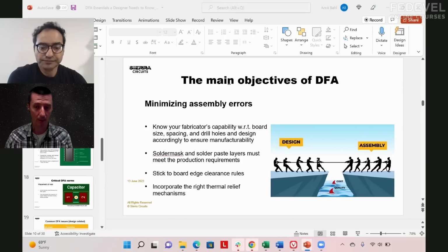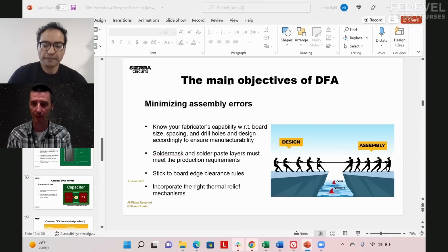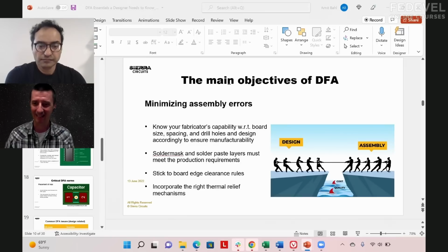Well, good. Because I remember also, as you said, it can be, for example, that a company buys a component in the wrong footprint. It has happened, but again, this is something I learned: I should always buy the components before finishing the board, because then I'm sure not only the footprint is correct, but also the part number. You really don't want to buy a thousand $10 chips and then find out you bought them in the wrong footprint. Yeah, no one is going to take it back, or if they do, not for the original price.